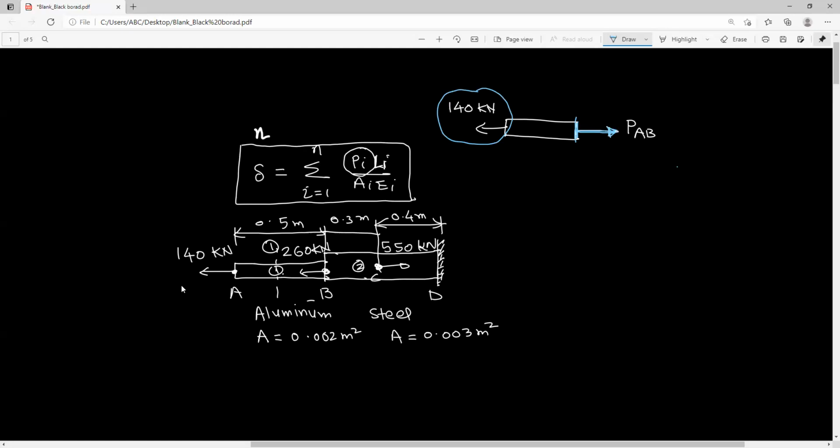We always consider the positive sign convention as tension, and it will come accordingly. Somebody may ask why we have not taken the reverse arrow and why we have taken only this arrow in this direction. Because it's the cross section and the outward force, and that will also impart tension within the bar. And we take the equilibrium of these and we can calculate part AB.